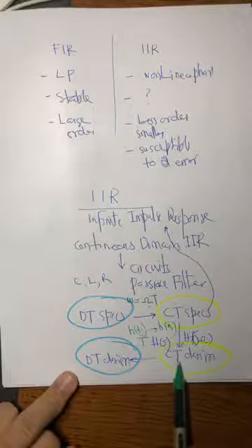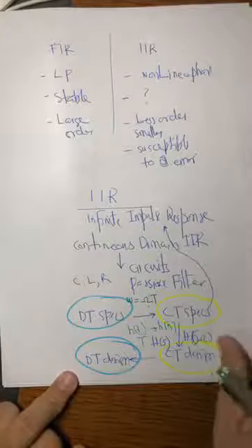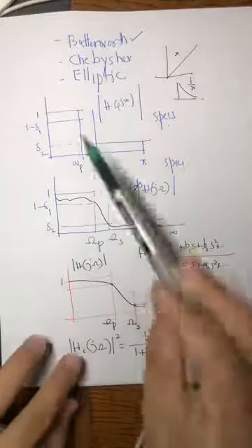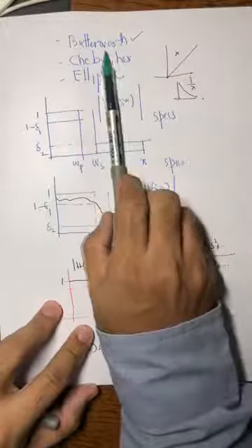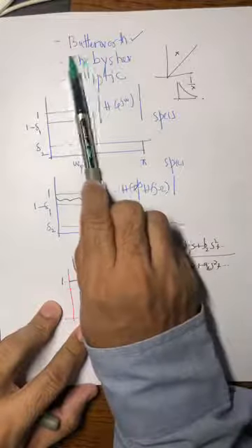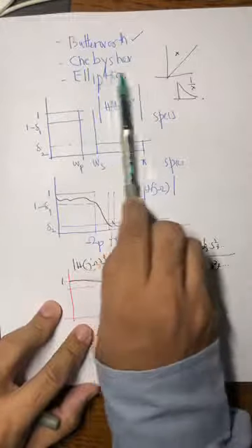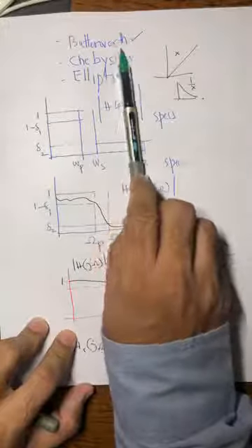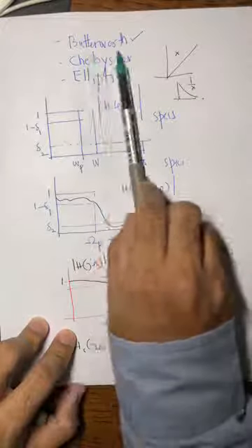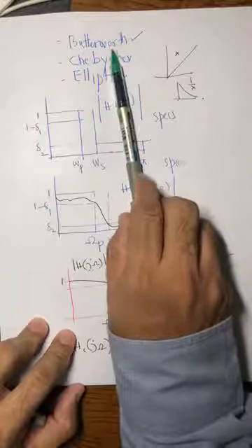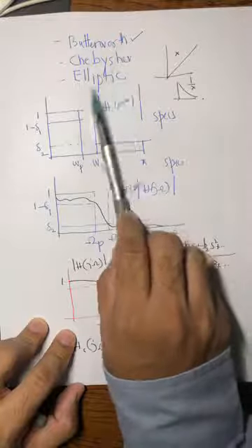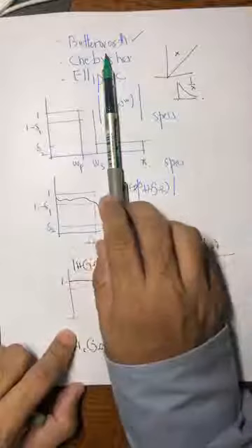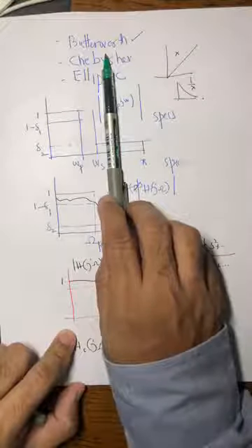So last time we covered how you design a filter in the Laplace domain or S domain. Okay, and so we said these are the three famous analog filter design techniques: Butterworth, Chebyshev, elliptic. Okay, Butterworth, I told you, must be a very genius person. He came up with the technique of designing an analog filter, converting a mathematical expression into actually a circuit which has capacitors, resistors and inductors in it, basically passive filters.